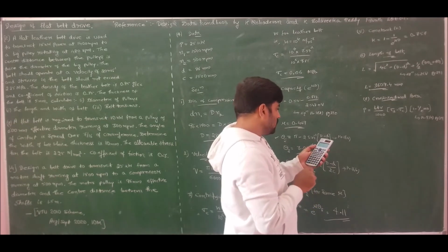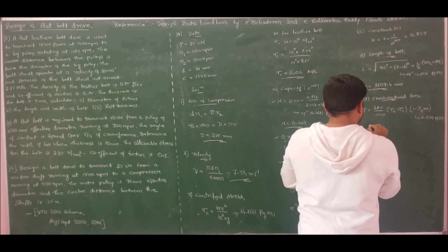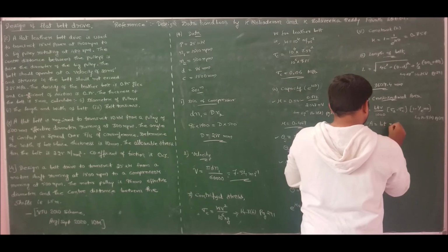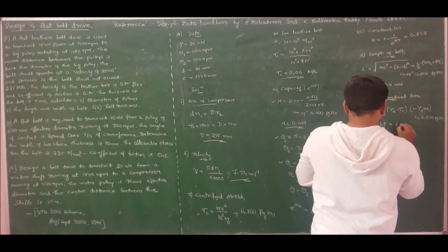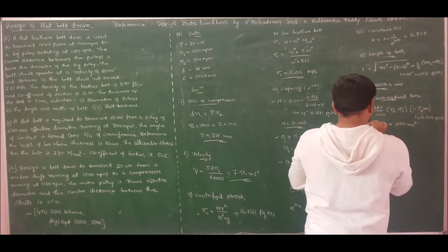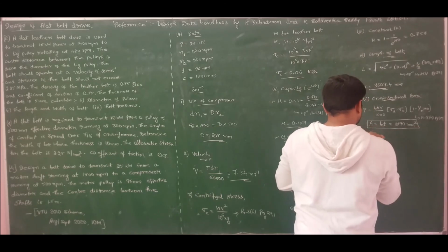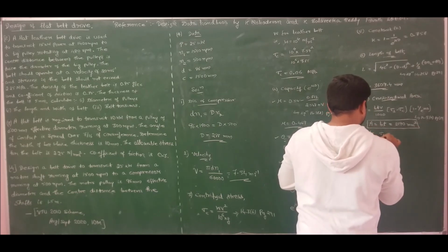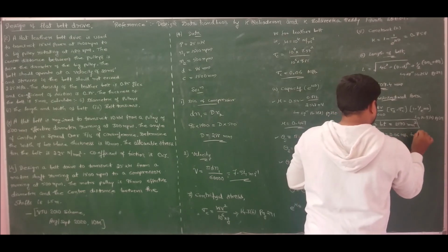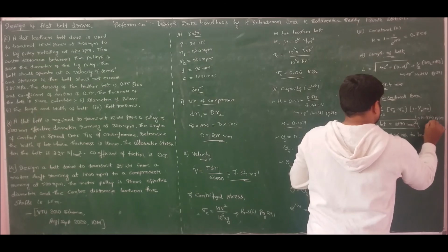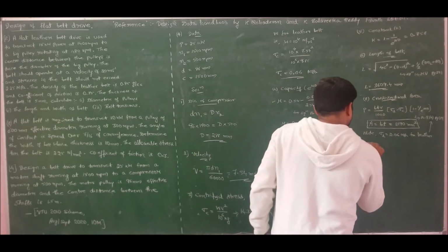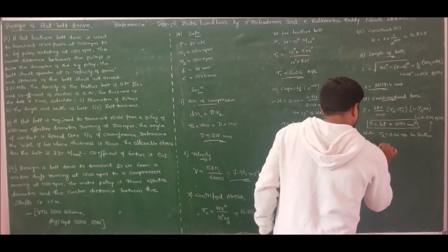If I solve, I will get the cross-sectional area A, which is B into T, as 2190 millimeter square. Now sigma D is 2.06 MPa for leather, which is given in this equation itself. So next, moving to the final step, to find the initial tension.